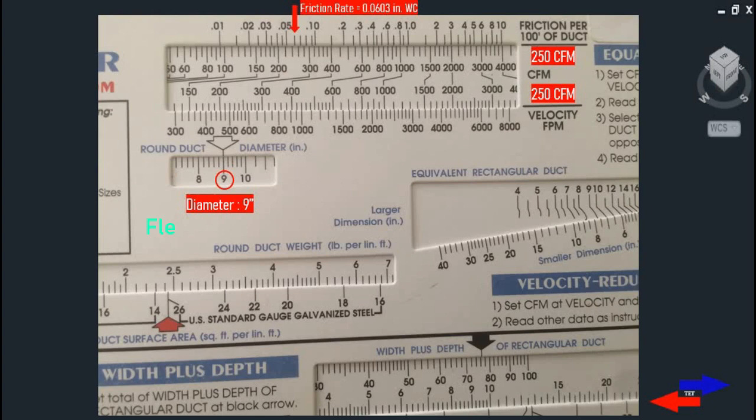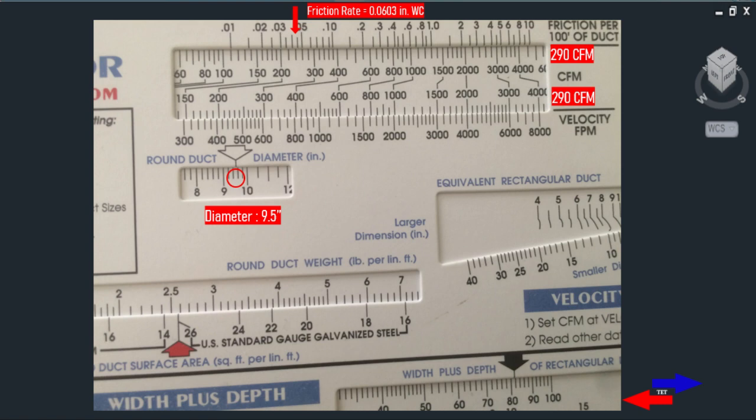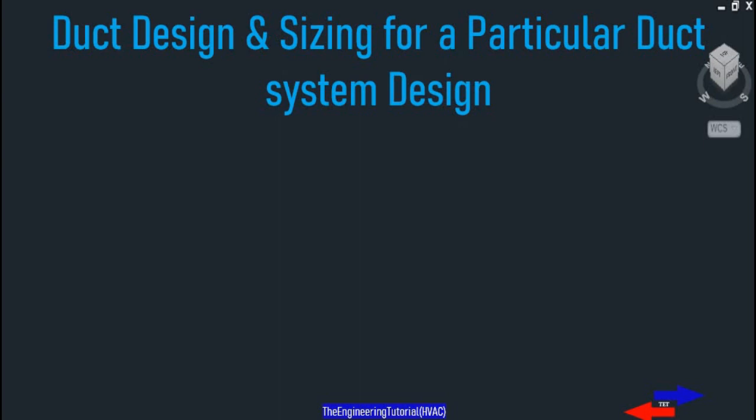So in this case, instead of a 9 inch round sheet metal duct, we can select a 9 and 3/4 inch flexible duct.